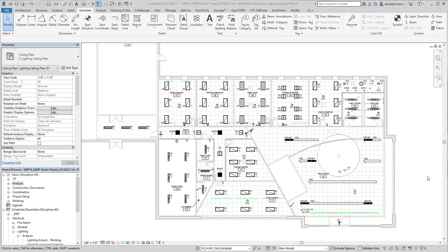In this video, I'd like to unveil, in the new MEP Productivity Pack 2018 update, the new universal lighting fixture content that we have developed. In one family, we now have the ability to have both a hosted and unhosted lighting fixture with a native light source, so not a nested light source, which makes it easy to update the photometry and also do lighting calculations when needed.